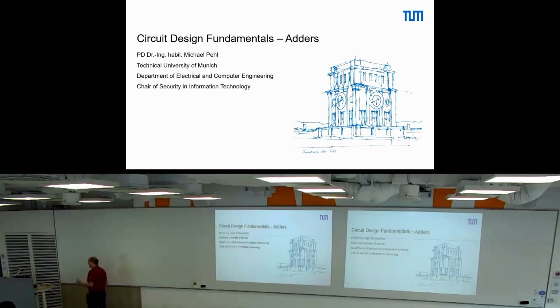If we now compare the ripple carry adder to a carry look ahead adder, what are benefits, drawbacks there? Propagation delay, benefit or drawback? Drawback, it depends. Yes, we have a long fan in and fan out. That causes for large CLAs a long propagation delay.